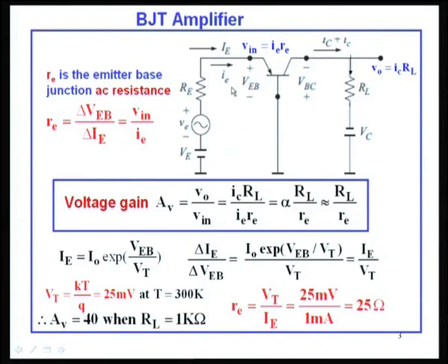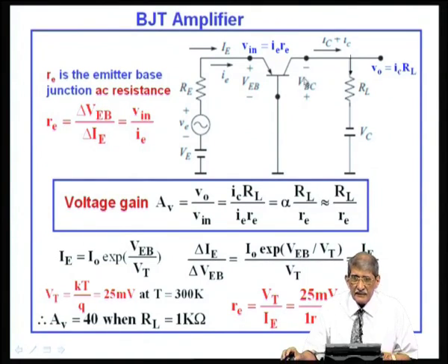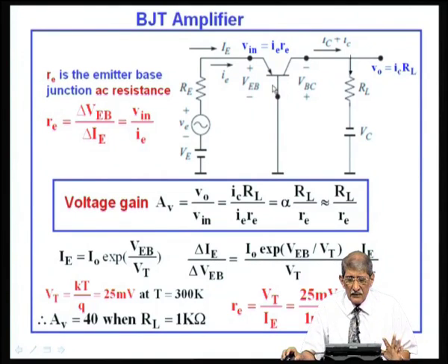Suppose the DC current is 2 milliamperes, what happens? If the DC current is 2 milliamperes, the DC drop across this increases to 2 volts. So, if this is 4 volts, the voltage across this will be 2 volts DC. But this ensures that even though this is reduced from 3 volts to 2 volts, this junction is reverse biased. So, the transistor is still in the active region. So, I C will be equal to I E practically, and small i c will be equal to small i e. Therefore, the same equation holds good in this case.